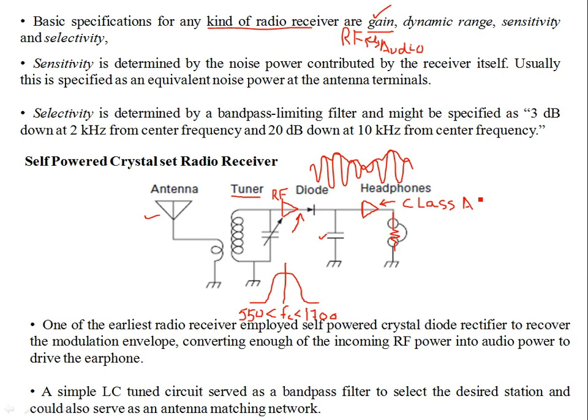These are linear amplifiers, so you are not going to produce any unwanted harmonic content. For a high fidelity signal to drive the audio load, you might need a class AB, class A or class B amplifier. So you have two kinds of gains, RF and audio.